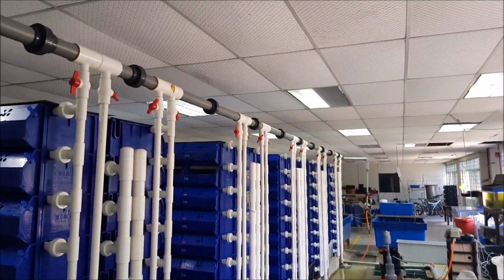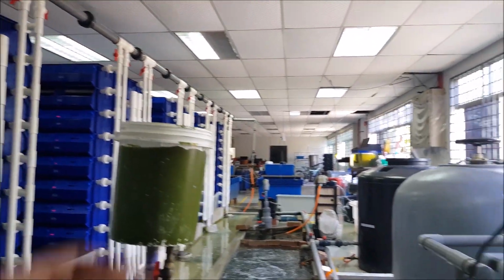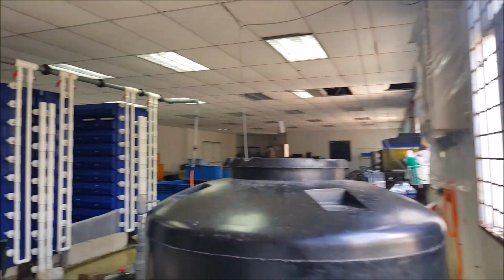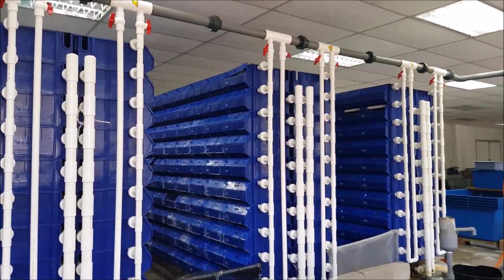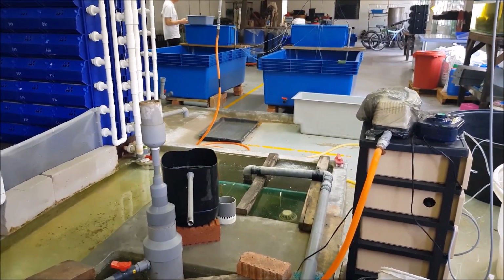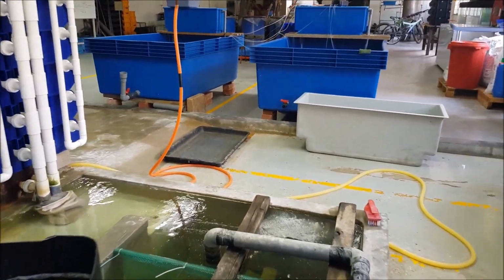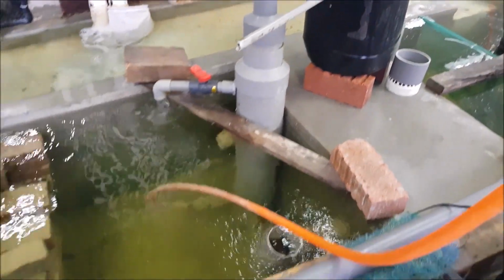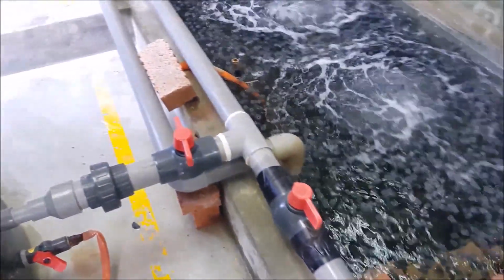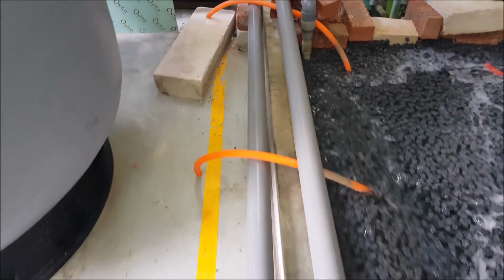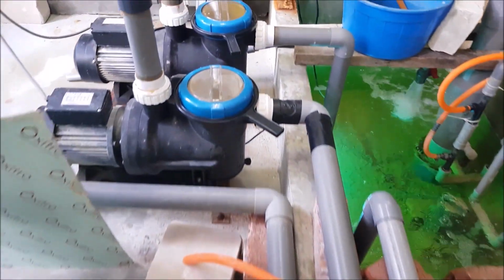This is just a back view on how the water is being distributed into each individual row. Now we're going to take a detailed look at the water treatment system by first looking at where the outlet water goes. The water exits the pipe via the outlet tubes and goes to what we call the retention tank, and whatever flows to the retention tank then flows through the first stage, which is solid removal via this piping. We'll follow this pipe from the first retention tank all the way to the first pump. This is the inlet of the pump.